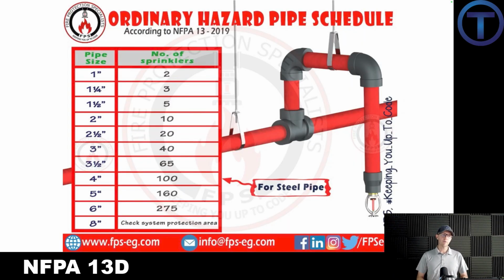Have a look at this simple illustration of pipe sizing. This is coming from the fire protection specialists. You can reach them if you want to order or get more information about fire sprinklers, but this diagram illustrates a table here taken from the NFPA 13, and you've got pipe sizes listed down the left with the number of sprinklers that can be put onto those respective sizes on the right. Notice for a 1-inch pipe, you can do 2. As you go to 1 1/4, 3, 1.5-inch pipe, 5, and so on. You can see how as the pipe gets bigger, there is going to be a limit to how many sprinklers are attached to that, but then you know what pipe sizes you would need depending on the number of sprinklers.